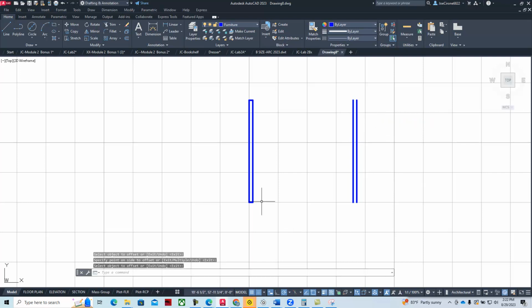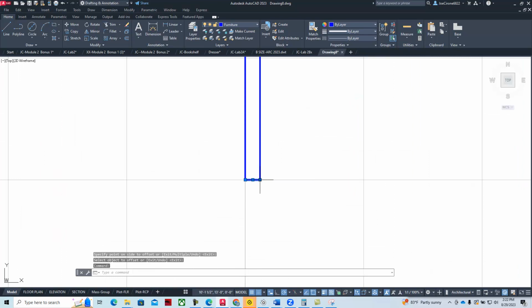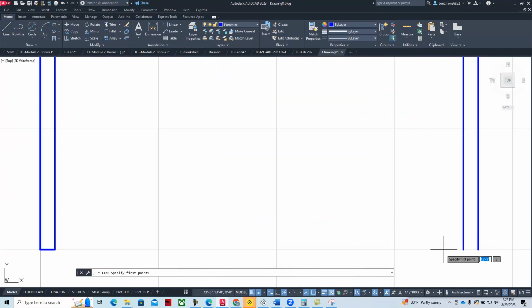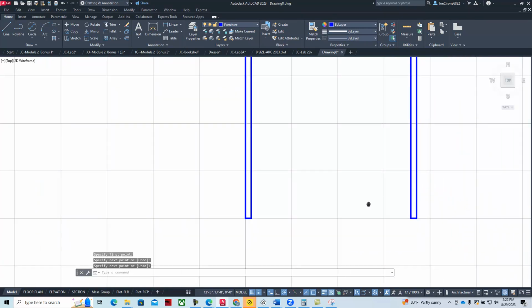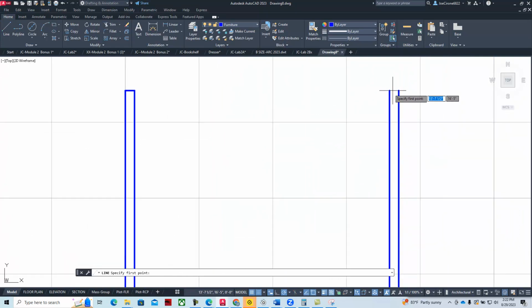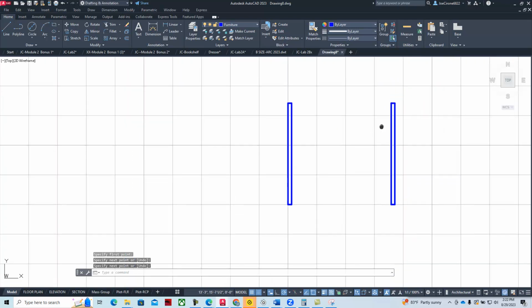And I just want to verify this one to make sure I did that one right. Yep, it's 1.5 inches also. And that's what's nice about the CAD system. It's very accurate, and it's easy to go in and obtain measurements. So I'm going to draw a line from this endpoint to this endpoint. Right click, enter. I can turn the wheel, I can pan, and it's kind of like working with an Xbox or something where you're working with a controller and you're using the left mouse and then the right mouse and enter.